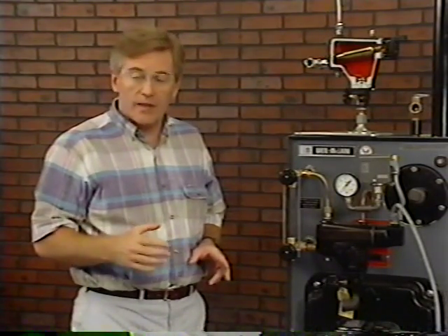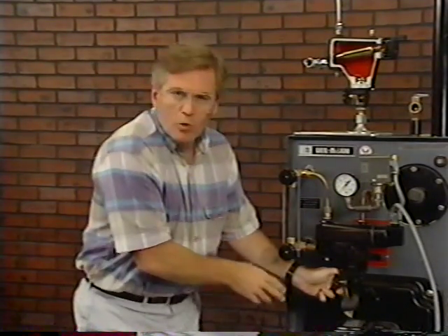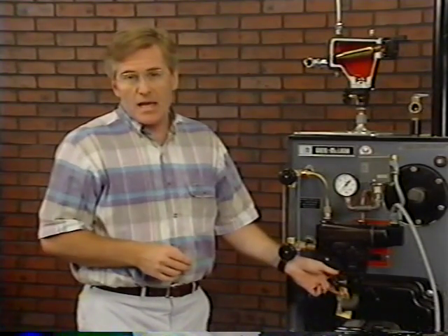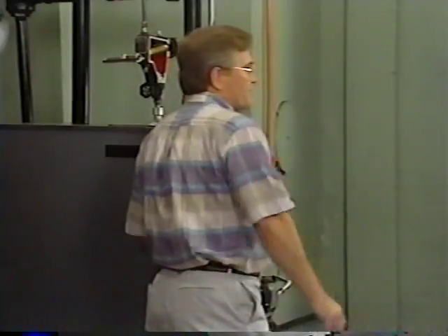Low water cutoffs require periodic maintenance to rid the float chamber of sediment that can collect and cause a low water cutoff to be inoperative. Periodic flushing or blow down of the float chamber is recommended during the heating season. In a new installation, a daily blow down is recommended for the first couple of weeks. It's to make sure the low water cutoff float chamber is clean, due to sediment that can break loose from the old piping and collect within the boiler and the low water cutoff.